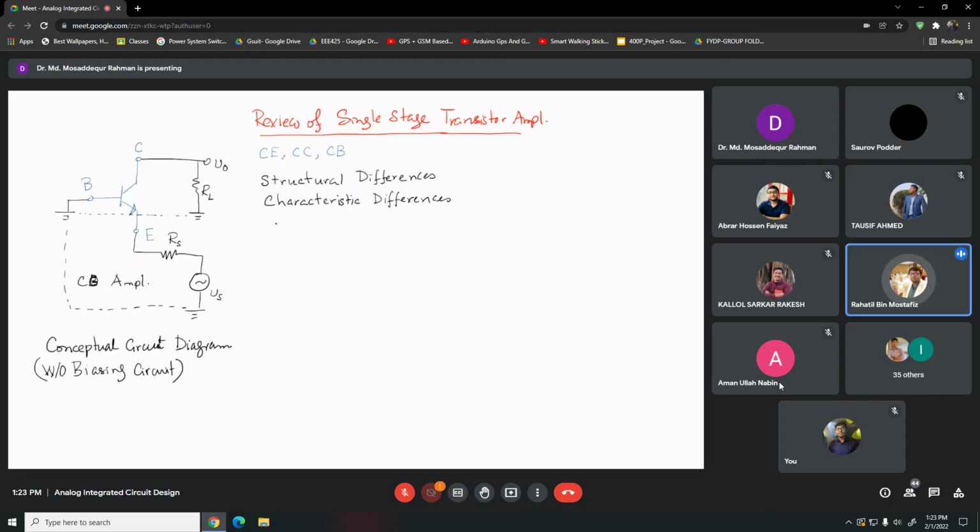There is a barrier voltage inside the transistor. We need to cross that voltage. So biasing is needed. So you need to forward bias or reverse bias the PN junctions, right? With DC voltage, right? So unless you forward bias, reverse bias the junctions with the external power supply, right? The transistor as it is cannot work, right? They will not respond, right?